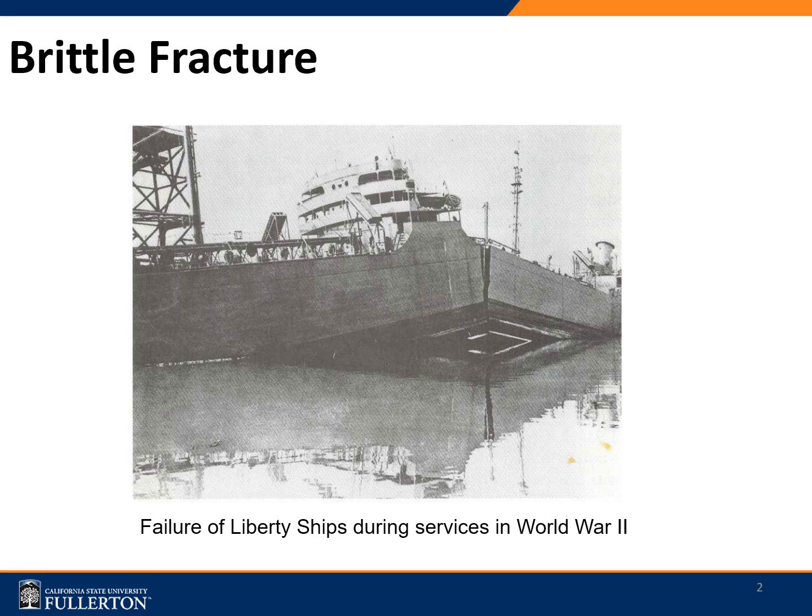So why is brittle fracture important? The primary reason being, unlike the traditional tensile failures, where the material plastically strains under overload conditions and then becomes thinner, undergoes necking, and then finally leads to rupture, in the case of brittle fracture there is no thinning, no necking. Instead, the damage mechanism is often caused without any warning, and the resultant failure is a catastrophic fracture.